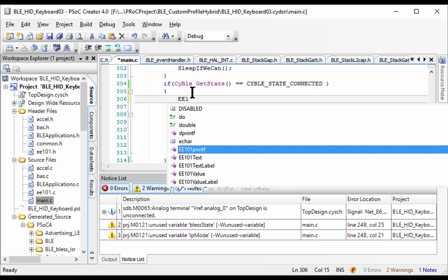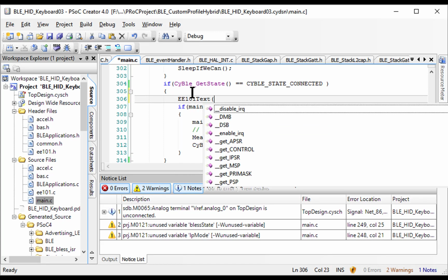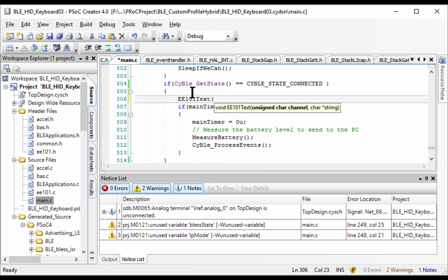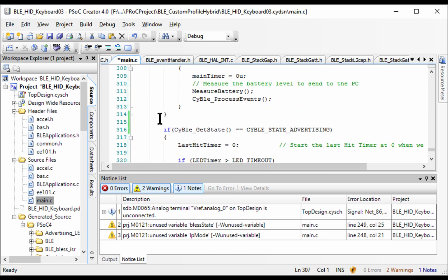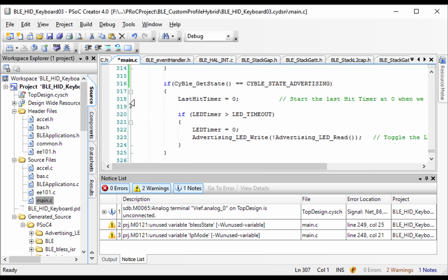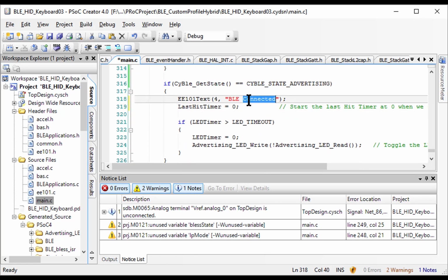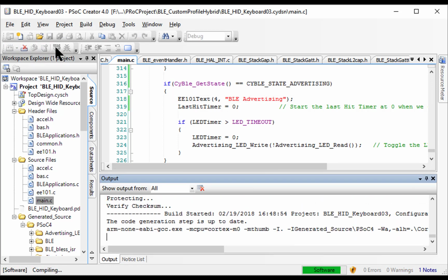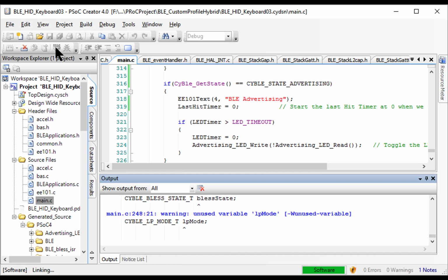So now we're going to get a little more intricate. This is a Bluetooth device. We have a portion of code that is run when the device is connected to something, and there's another mode in which it is advertising in order to get connected. So we're going to output two debug outputs, one that says it's connected and one says that it's advertising. This allows us to see the actual state of this program.